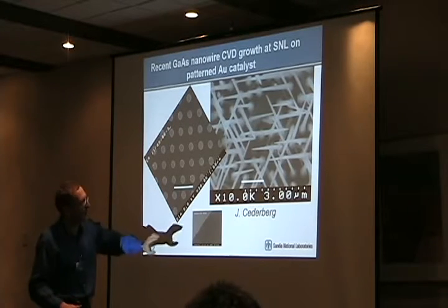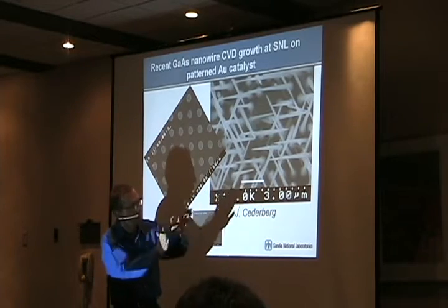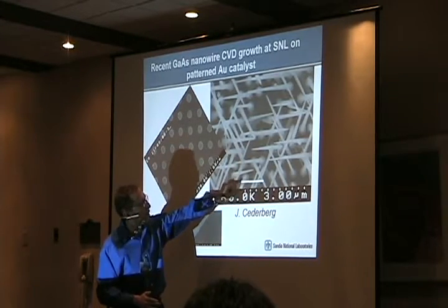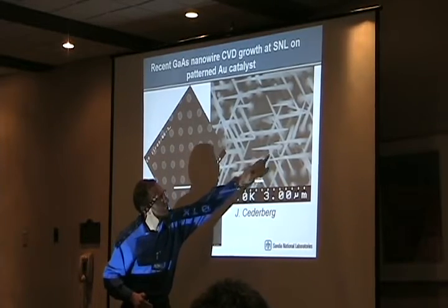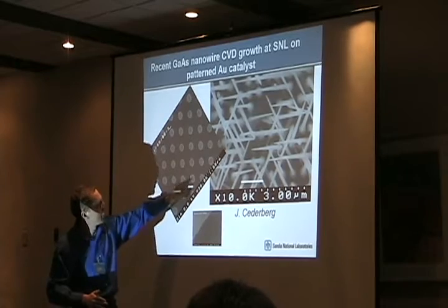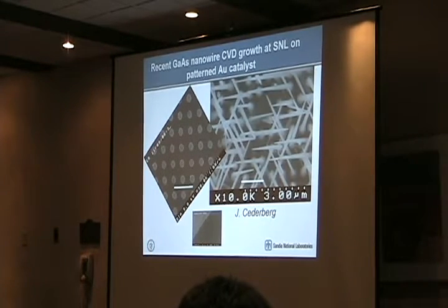If you look carefully where these nanowires are originating, they're all 111, but of course there are several 111 directions. There are 4 equivalent 111 directions. If you look at where these nanowires are originating, the spacing is exactly the same as that determined by the gold catalyst patterned on 111 gallium arsenide.